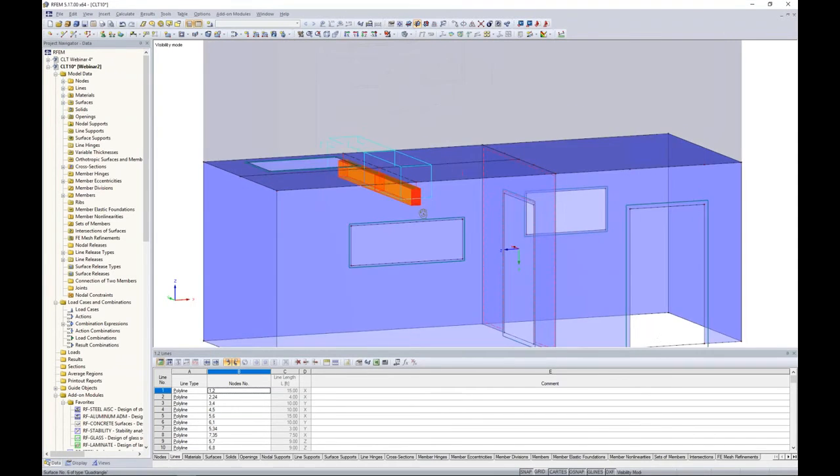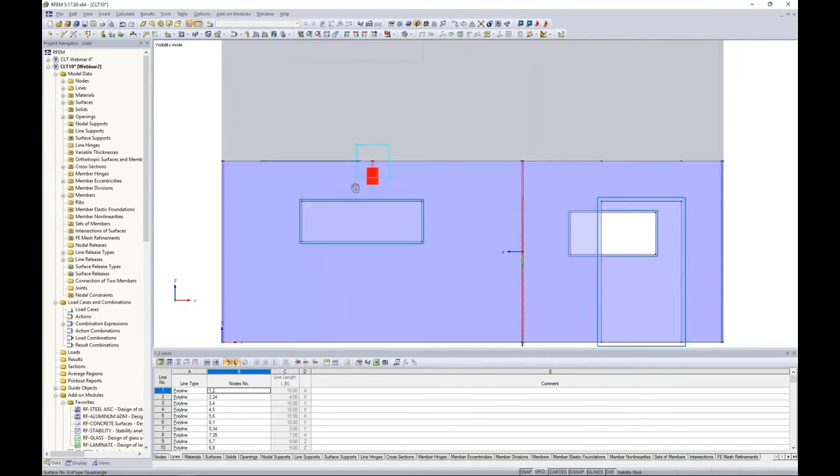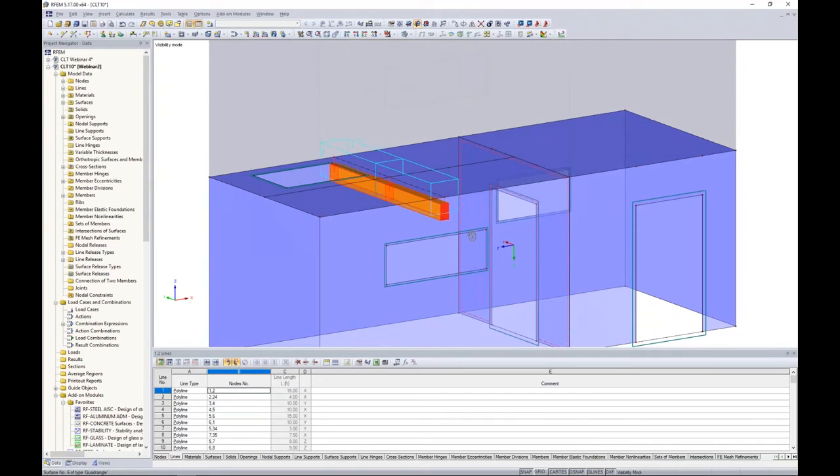So now we can see visually that beam dropped below that panel. So what's nice here is that eventually we're going to change these steel panels to CLT. Well, our thickness is inevitably going to change too. So instead of having to come back here and adjust the eccentricity, the program will automatically update everything for us.